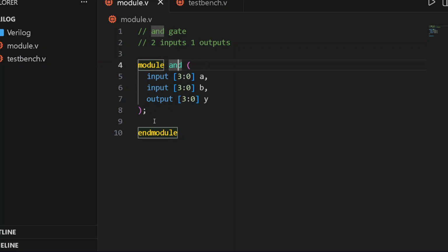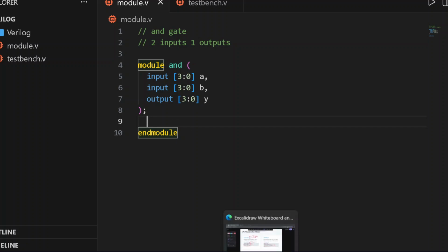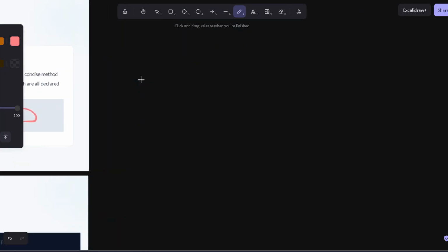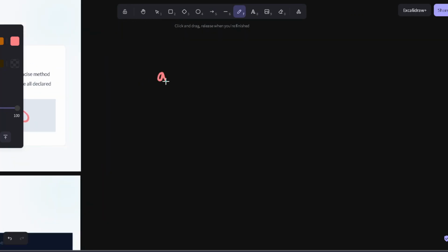Now you will say we have declared the input and output, but where is the logic? The logic is here. Here we will define the logic of our code. To show this, I will need to teach you one operator, the assign keyword. Later on we will see more of this. So what does the assign keyword tell us? The assign keyword basically allocates the logic to our output pin.